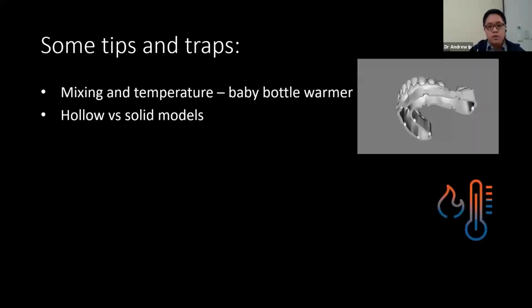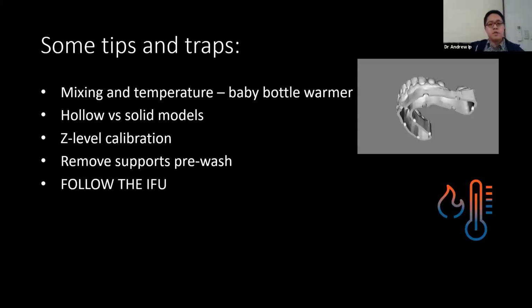Okay, and basically some other tips. Resin needs to be warmed. Now we're lucky in Australia; we're in a relatively warm country. But if you're in Canberra, in the mornings it can be bloody cold. So in some areas, you will need to warm up your resin. And for some printers, like the Asiga, it has a warming function already. But if you're using a cheap printer, you're not so lucky. So in those situations, you can use a baby bottle warmer to warm up your resins in a very safe fashion, and then you can print more predictably, okay?